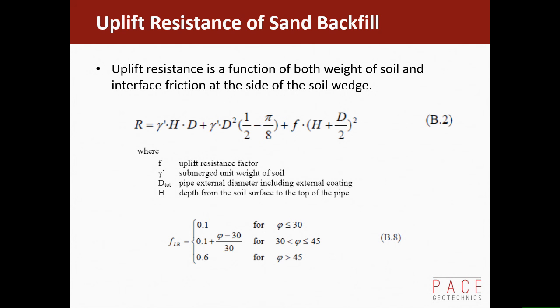So this gamma dash, second gamma dash, is the same as the first one? Yeah. Submerged unit weight of the soil. It'll usually be a little bit lower than the value you get from a site investigation, because by digging it out and pushing it back in, you've remolded the soil. Then what you have in this section is that.